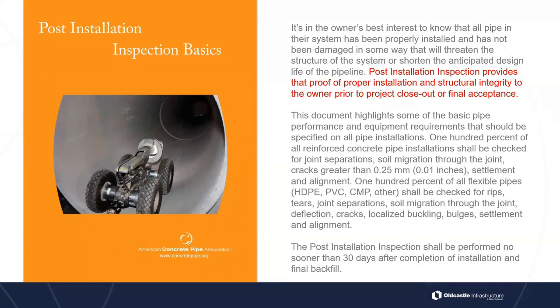This is another report put out by the American Concrete Pipe Association, Post-Installation Inspection Basics. And it says the post-installation inspection provides the proof of proper installation and structural integrity to the owner prior to project closeout or final acceptance. So if you're the project engineer and it's your responsibility to ensure that this was installed correctly, one of the best ways to do that is to require post-installation inspection and look at what you should be checking there.